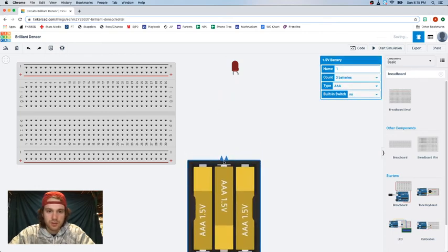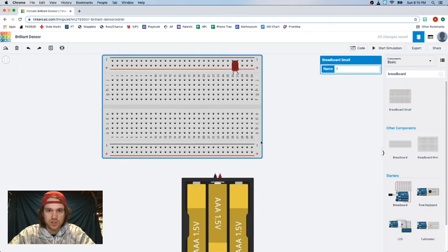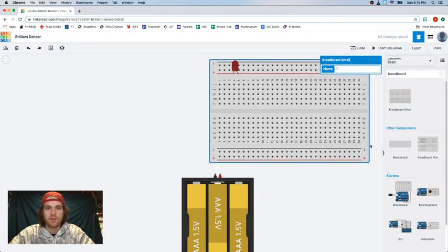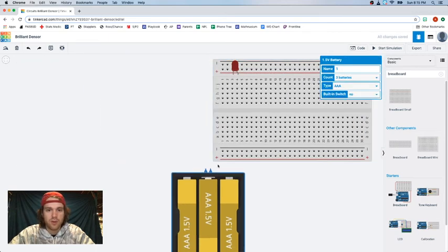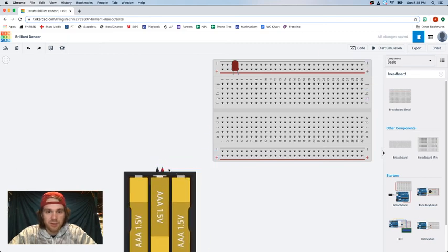All right, so I'm going to have this battery pack here. Positive. Actually, it makes more sense for the breadboard to be on the right so we don't have to cross wires here. There we go. I'm going to have the positive end of my circuit come up this direction and turn right 90 to connect there, and black connecting to my power rails. It doesn't matter which side you connect to.